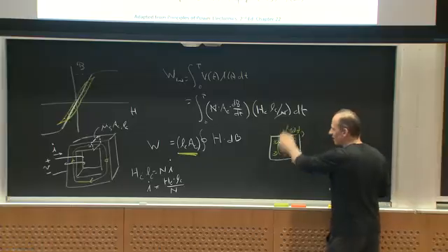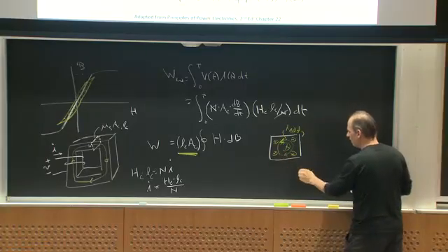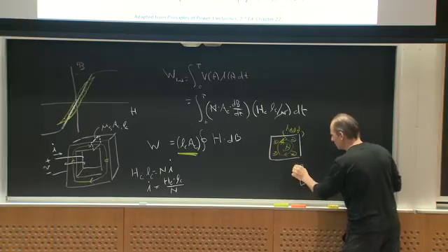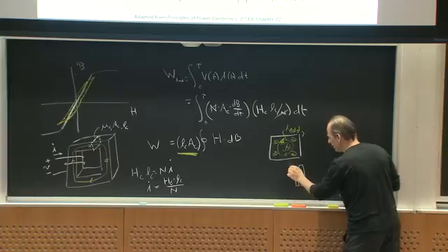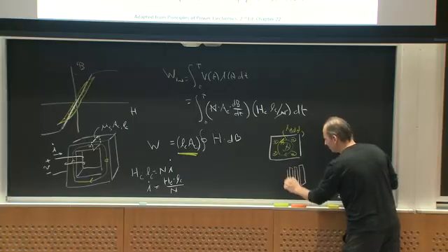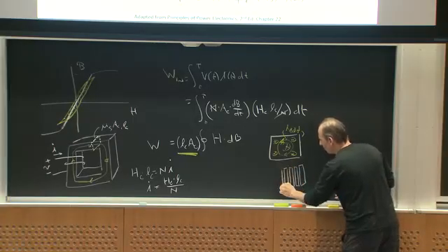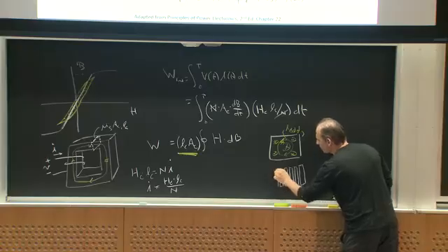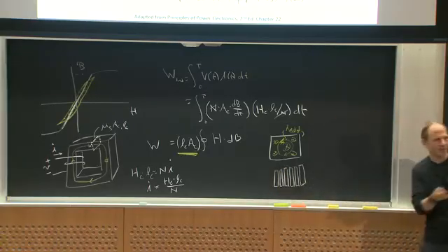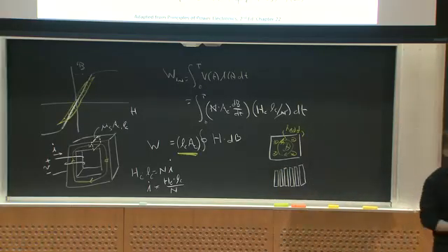What they'll do is, instead of making a big cross-section, make this out of little sheets like this that are insulated from one another, called laminations. So instead of building up a big fat piece of steel, they'll build it usually out of stampings, insulate them, and then stack them up.